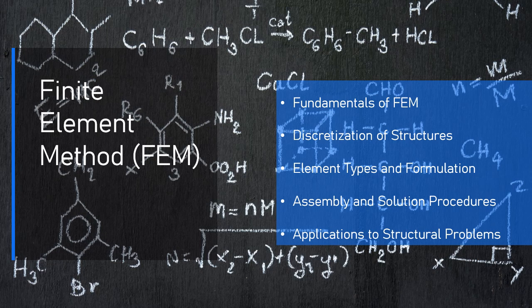4.4. Example procedure: simple beam analysis. Let's walk through a simplified FEM solution procedure for a cantilever beam with a point load at the free end. 1. Discretize the beam. Divide the beam into several finite elements, e.g., 2 to 4 beam elements depending on the desired accuracy. 2. Formulate the element stiffness matrices.